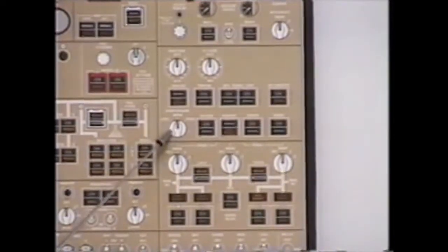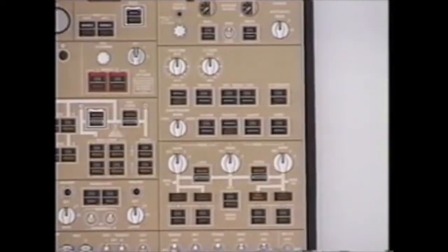Equipment cooling to the standby mode forces it back inside if that fails to happen. Equipment cooling to override shuts off the supply fans and exhaust fans, shuts off the supply and exhaust valves, and as a result, equipment cooling is dependent on differential pressure. If differential pressure is low, equipment cooling is low. The greater the differential pressure, the more efficient equipment cooling.